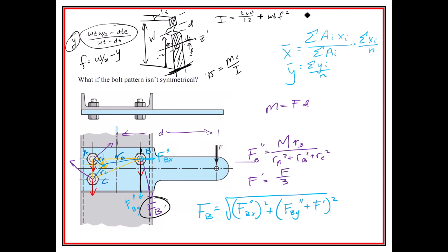All right. And then we're going to subtract out the area moment of inertia there. That's going to be base times height cubed, so it's going to be T times D cubed, over 12. I said squared, I meant cubed. And now that's going to be plus. Now we need to shift where this guy is from his center down to this new Y position right here, where I'm calling this distance Y. So that's going to be D times T times the shift that I made, so it's going to be E minus Y, and that's squared.